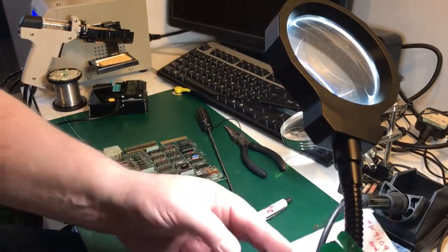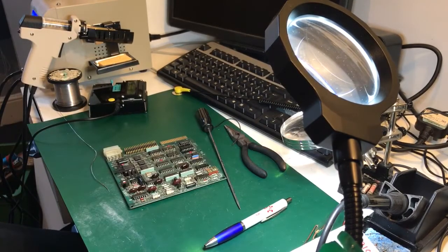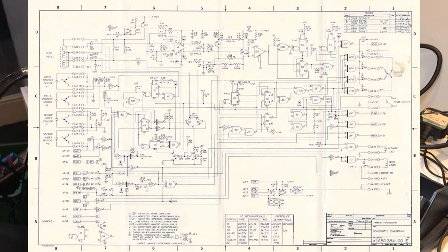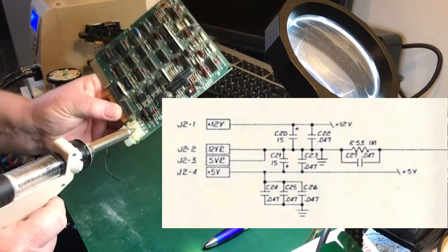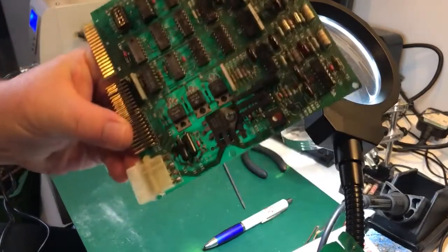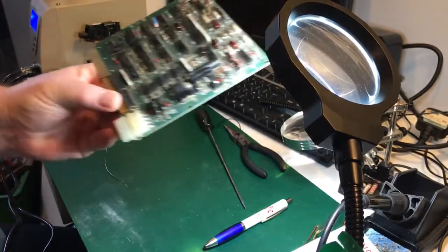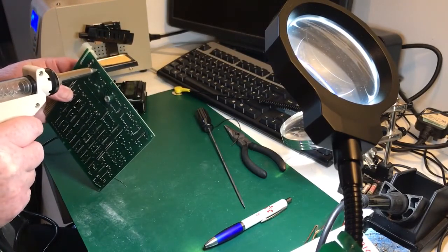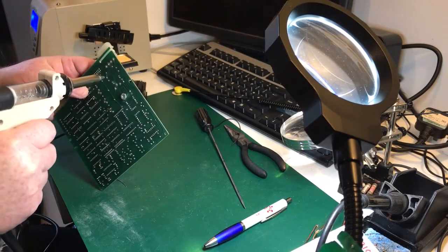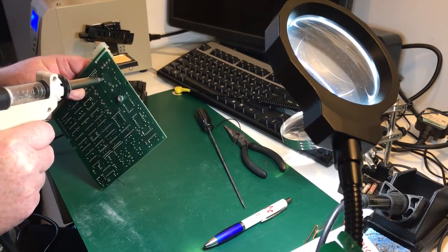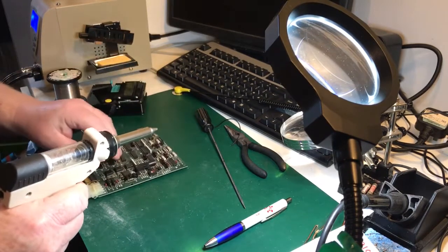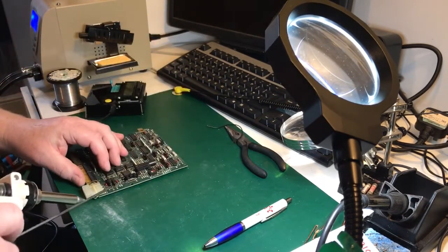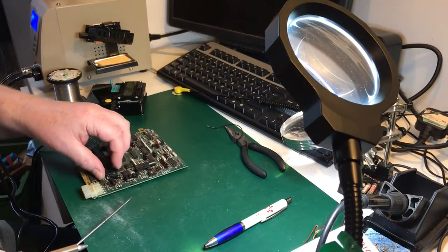Okay, I think this is not the board that we've got the online circuit diagrams for, but as a minimum we're going to take off the known dead caps, and I'll probably take C23 off as well, just because C23 looks a little bit charred next to C21. Can't quite see the values, that's going to be a shame, but never mind. Blown cap should come out. You might be able to see the value of it once it's out of the board.